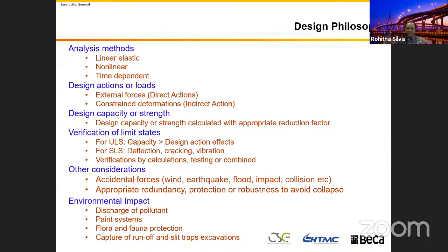When you design a bridge, it's time dependent, and you can take creep and shrinkage into account and incorporate that into the bridge model. So when you model the bridge in 3-dimensional modeling, your pile foundation is in the soil, so you have to get the soil interaction. You can incorporate that into the model.